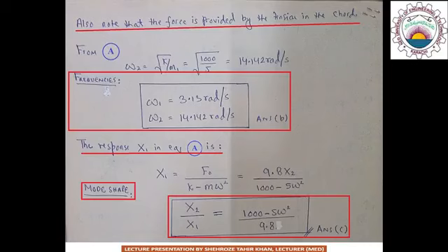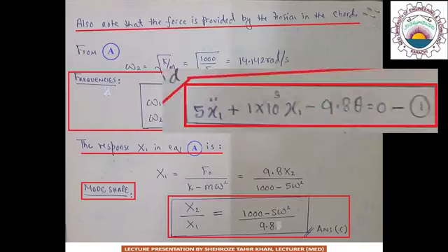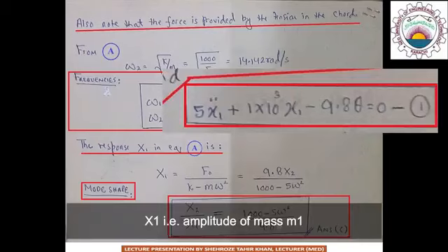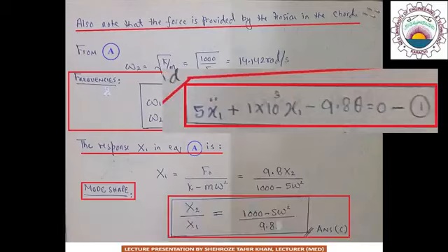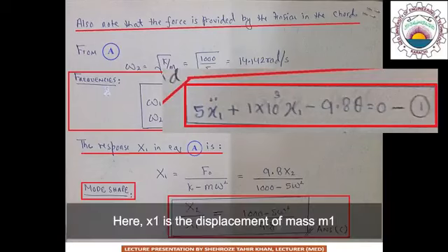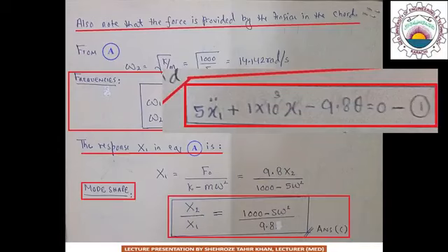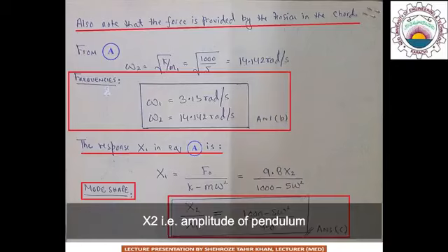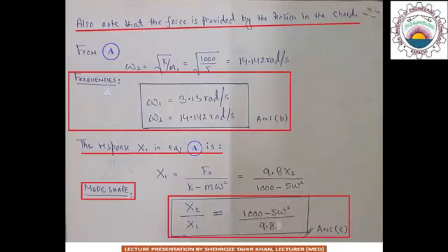And number 3, from the equations of motion, it is observed that the motion of x1 has no effect on motion theta. However, the motion of theta affects the motion x1, hence theta is the controlling variable in this problem. Therefore, x2 can be the initial condition for the system, and the motion of the pendulum will reduce the forced vibrations in the mass m1.